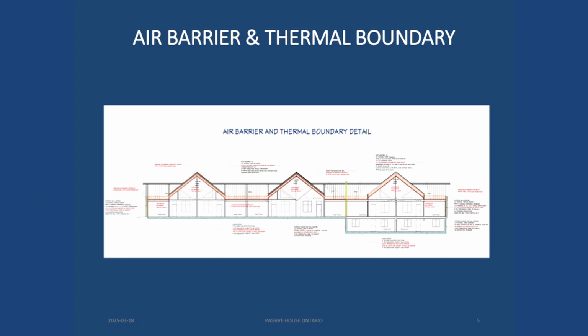So it shows how things change from the wall system to the roof assembly, through the slab assembly, through the foundation walls. Maintaining insulation or air barrier continuity through similar components, like wall to wall or floor to floor, is not that complicated, but as soon as you change components it can get really tricky. The control layers often aren't in the same place, and it definitely has to be planned. It's not the type of thing you can do after the fact.